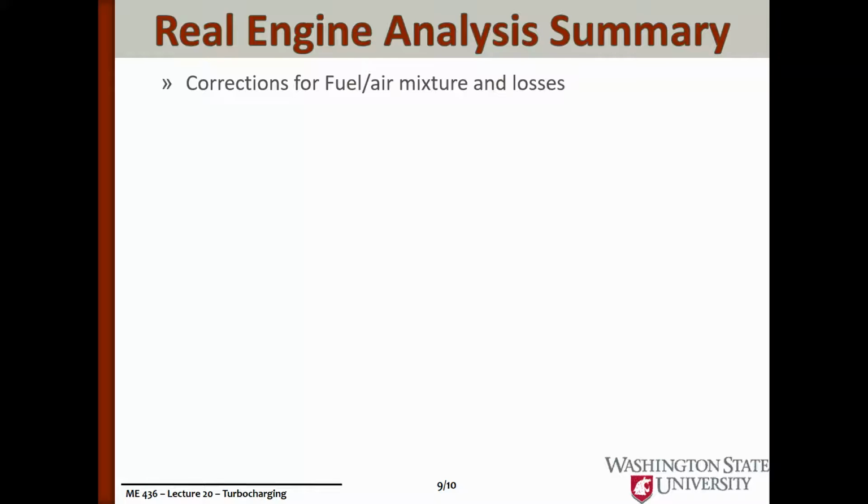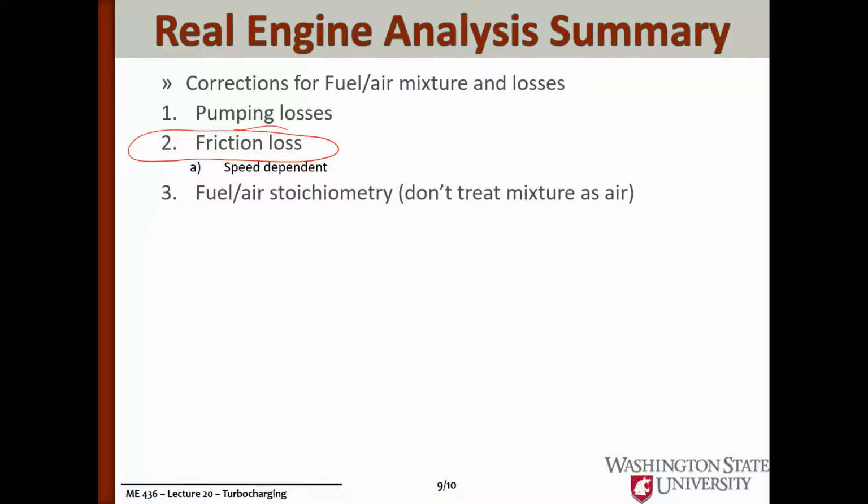real analysis. We worked on corrections for fuel and air rather than treating it just with air, so we worked with the diesel cycle. We worked with pumping losses. We talked about friction losses a little bit. We didn't delve into that too much, but they are generally a function of the speed the engine is operating at. We've lumped all of that into the mechanical efficiency of the engine, but that mechanical efficiency really isn't constant. So a more detailed analysis would treat that as a function of the engine's speed.